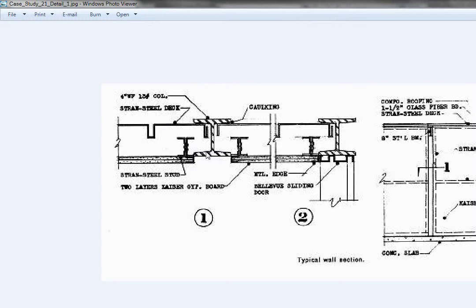Now what we're going to do is something fairly simple that fits completely inside this wide flange here. We're going to do a metal exterior with a light gauge metal interior, and then 1 layer of gypboard that sort of slides inside this whole thing, so we don't have to stop and start and stop and start. And we could make a more complex one, but we'll look at that a little bit later. Alright, so let's minimize that.